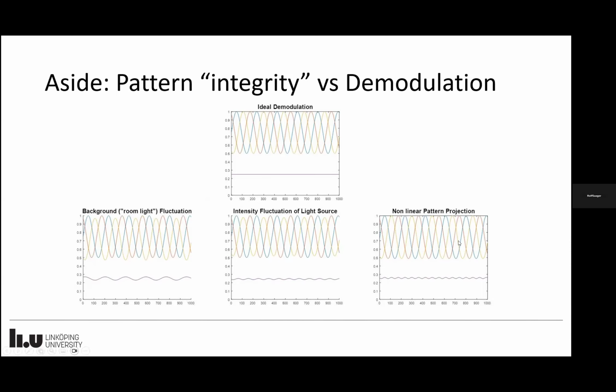The way that we verify it is we run through planar illumination patterns of the projector at different bit intensity levels, and map out what we're telling it to project. So something that is 10%, what do we get? 20%, and so on and so forth. That also maps out the nonlinearity of our camera. And then the final result is we can do the 3-phase.